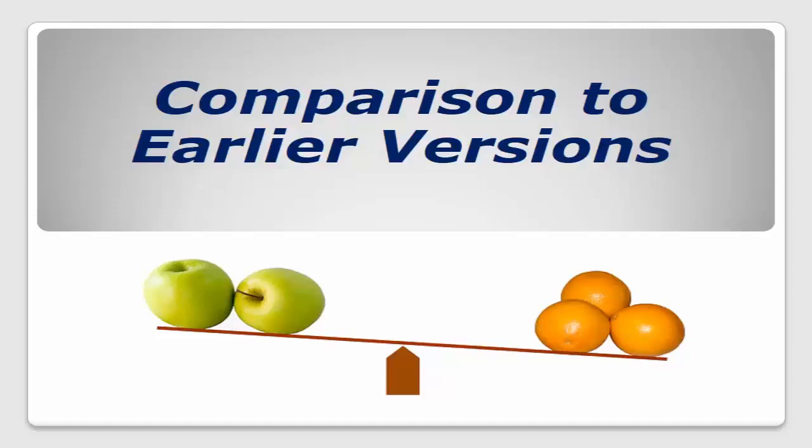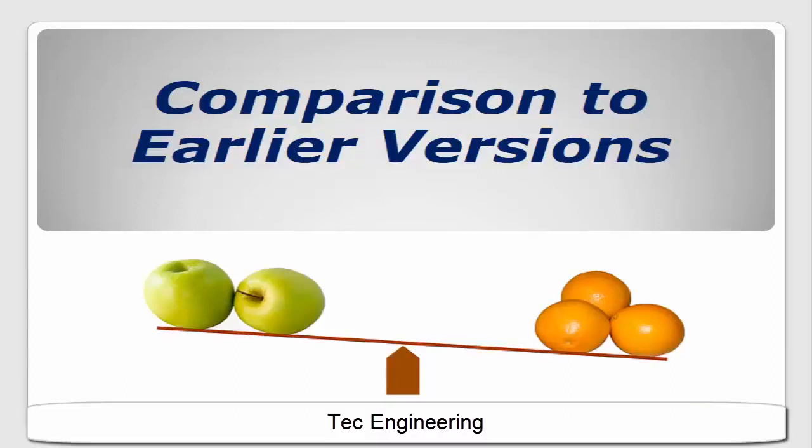If you're watching this because you work under a weatherization or home performance program, there's a good chance you're used to doing ventilation calculations using ASHRAE Standard 62.2. For many years, this was the method required by the Weatherization Assistance Program and referenced by BPI standards. New construction programs like Energy Star Homes and Lead for Homes specified ASHRAE 62.2, 2007, or the 2010 version. ASHRAE 62.2 2013 gives very different results from these older standards. It'll be helpful to understand the differences.